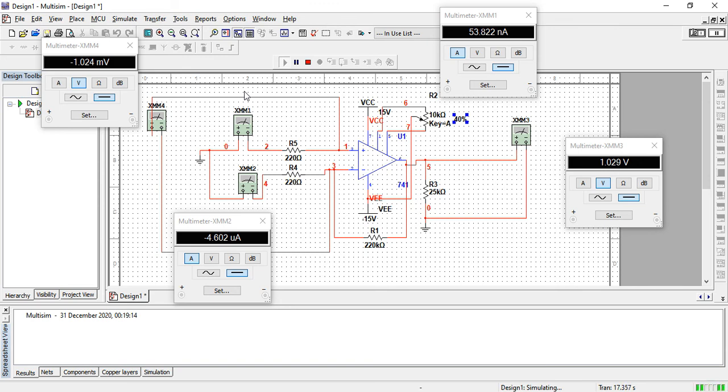There is a current between your input terminals and there's a voltage existing between them, and both of them are actually disturbing your output gain, okay? If nothing is attached and still an amplified voltage is coming at your output, it means that if you're giving a minor signal then it largely affects your output as well, right? So this is for your lab number 6 of op amp.